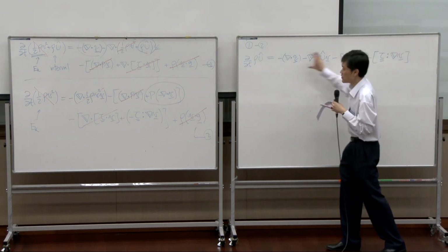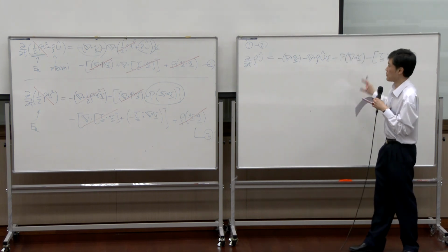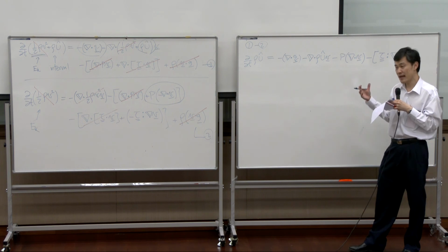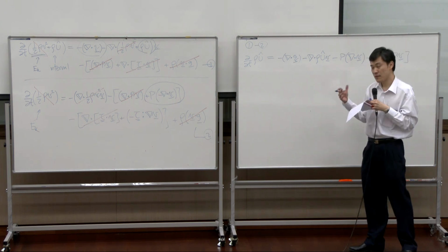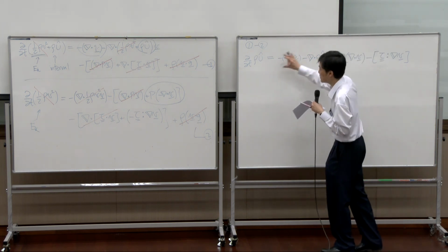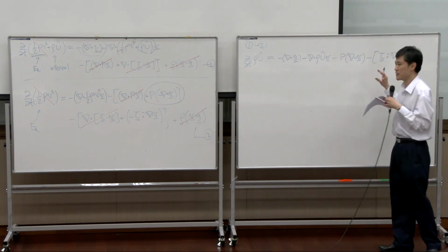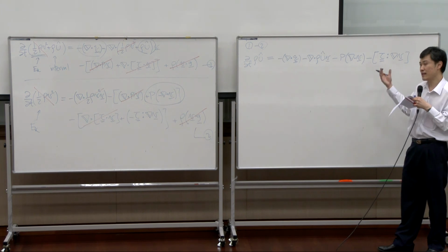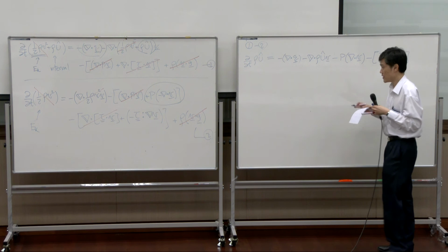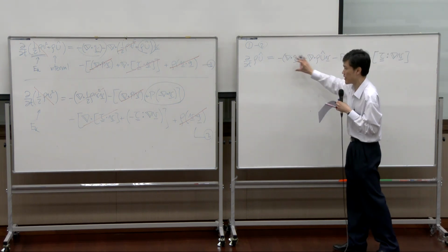So the whole equation here is basically equation representing energy change in the system, assuming that kinetic energy is not important, potential energy is not important, so it is applicable for system having dominating internal energy or system having temperature change. This is called equation of internal energy.